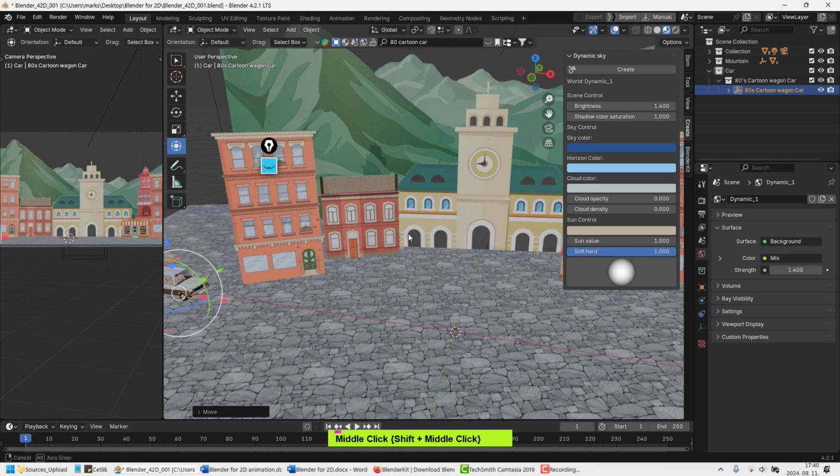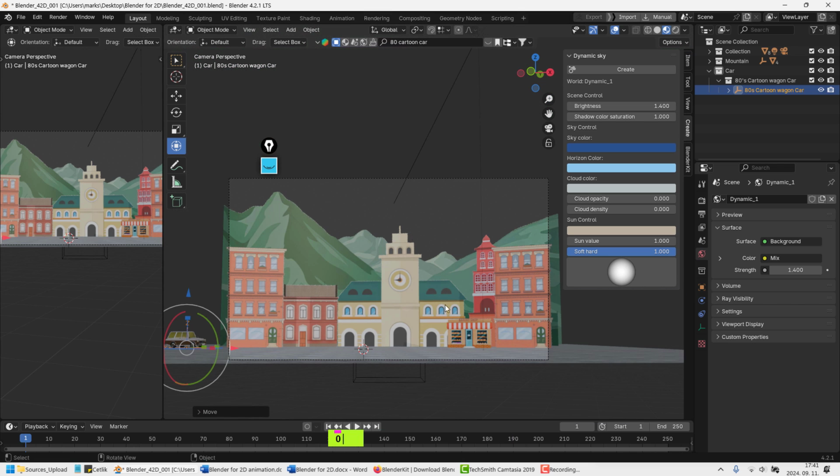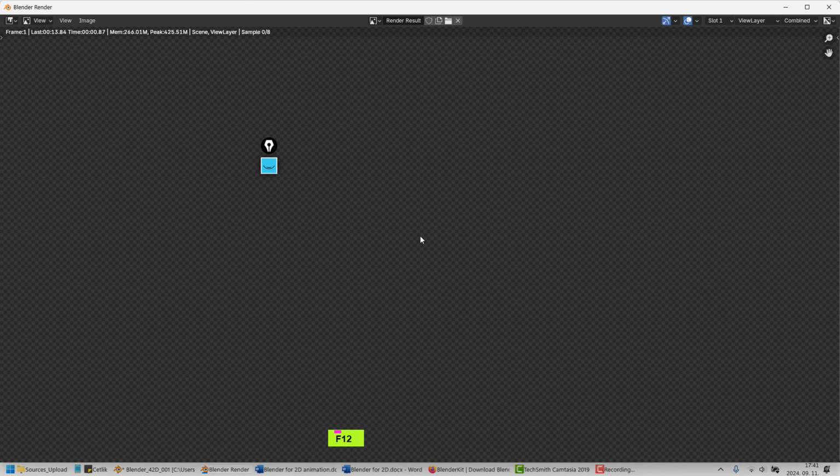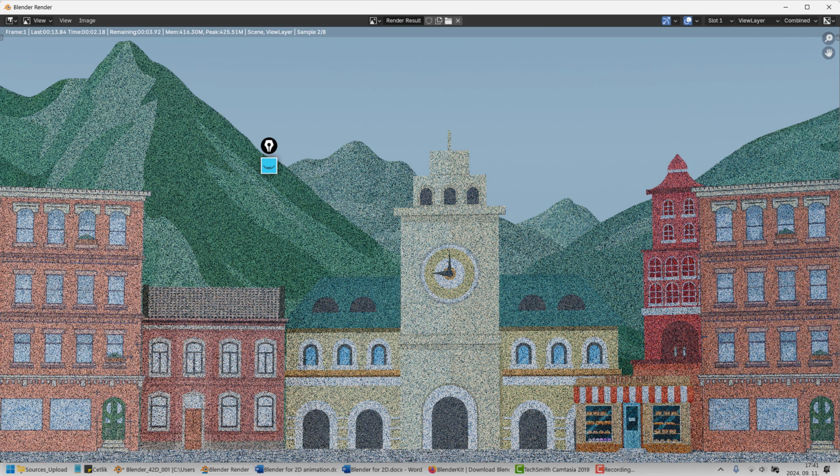Now global, let me go to the camera. And the frames, it's going from 1 to 250, and that's good, but we don't need that much, so I'll go to 200 only. And let me check the render time. For test rendering, we should check it, and it's fairly slow. So I go to Eevee.